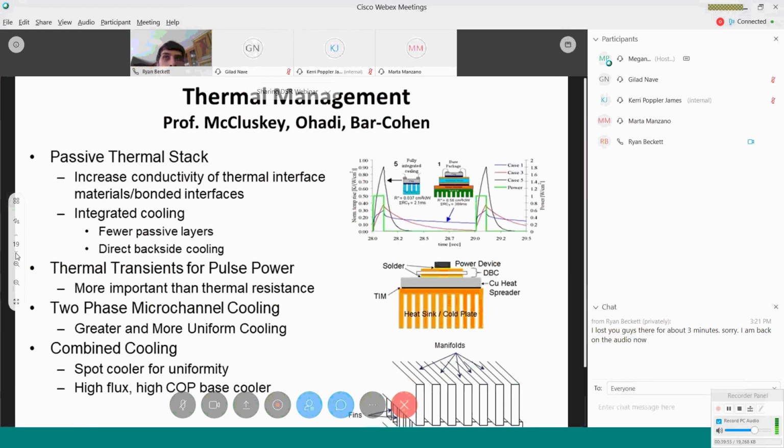Having made it, generating a lot of heat, maybe you have to put some thermal management in there, so we look at a lot of thermal management tools that can be used to remove heat from high-powered electronics, where a lot of heat is being generated. The first thing you can do is just stack those electronics up on a lot of layers that can absorb and dissipate heat. So you want a lot of materials that both have a high specific heat so they can grab heat from the device, okay, and then a lot of thermal conductivity so it can shed it out, okay.